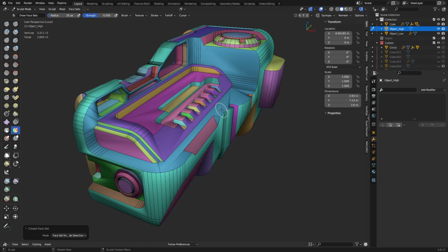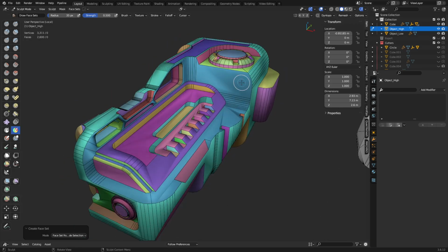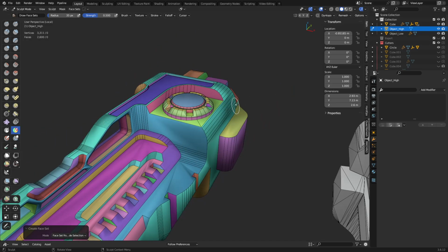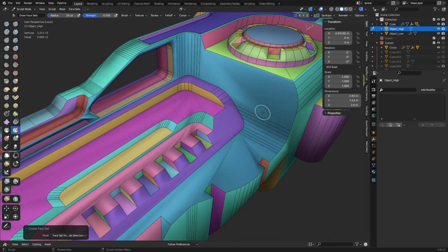Meaning for a cylinder, you use a screw modifier and a profile of the shape of the cylinder to make a non-destructive cylinder, right? You might use bevel modifiers with weights or vertex groups or by angle and set everything up in a way that you can modify the segment counts on your bevels or your cylinders or your spheres, right? So then you can create a low poly and a high poly virtually at the same time, or at least a smoother version of that mesh that you could remesh and not have to do as much smoothing stuff like this perhaps, right? All right, well, we're doing it this way, but